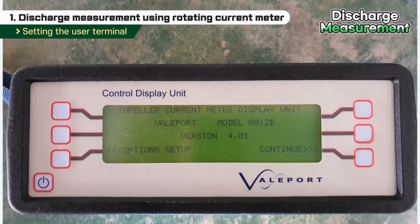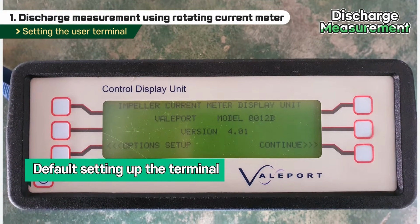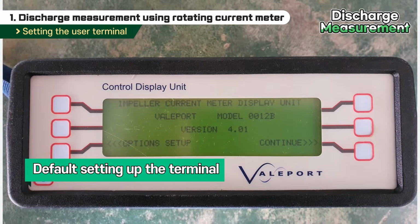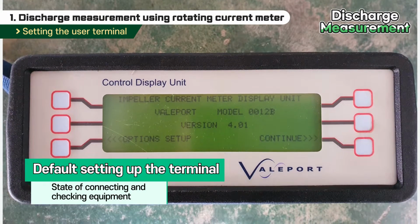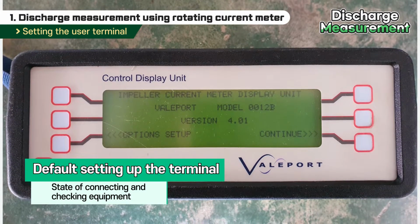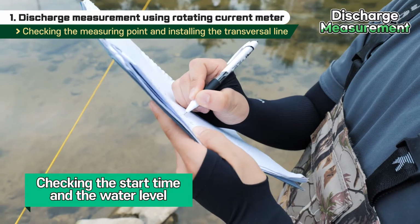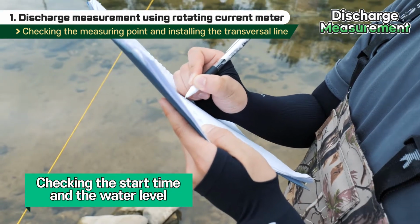After installing the transversal line and assembling the current meter, the user terminal is set to default. When turning on the terminal, the measurement unit, method to measure the current speed, and measurement time are set. Then the measurer checks and records the start time of the measurement and the water level.